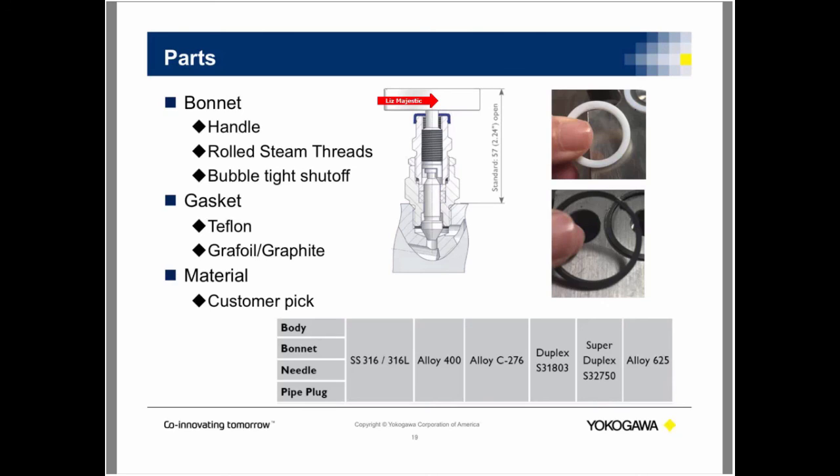The dominant failures are they leak, and the leaks generally happen with the gaskets or the valves. The valves weren't correctly packed and caused a leak in the valve. You can fix that by tightening the handle, torquing it down more, and then changing out your gaskets, because you can damage the gaskets if you don't torque or mate it correctly to the transmitter.